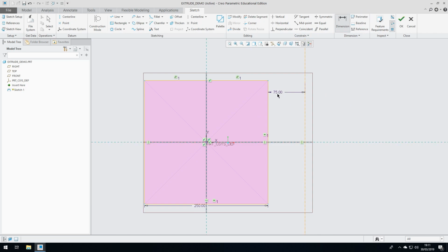But if you were going to mirror, you could set your gap, so half. If you wanted 150 mil there, that would be the right number. And you can do reference dimensions as well, which are not driven, so they won't change anything, but it will just give you an idea of what the value is.